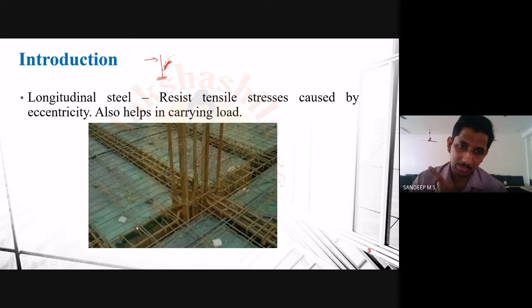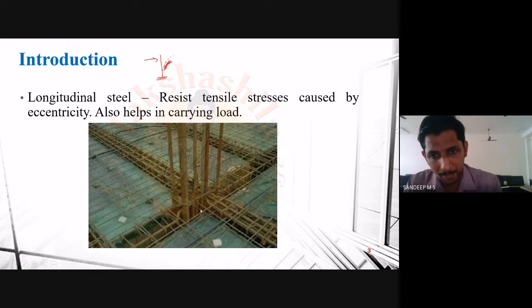So if you observe, the main reinforcements in the beams are actually bent and taken inside the column. You must always do it like this. You must not bend the longitudinal steel in a beam around the column. As an engineer, it is mentioned that we should not allow this reinforcement to go outside the column. It should always go inside the reinforcement which we provide in a column. So this is one thing that you have to note from this.